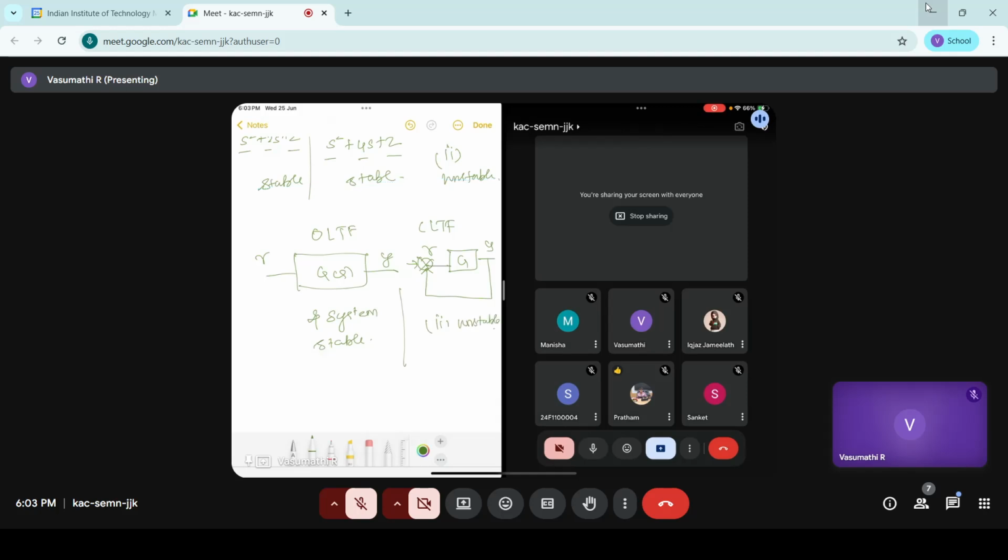So sometimes this feedback creates a disturbance inside the system that makes a marginally stable system go from the midpoint, the marginally stable, to unstable. That is the case that happened in the right hand side. So this is some intuitive explanation behind that. The marginally stable can anytime be stable or unstable. In the system behavior, based on the other pole location, it pulls the system towards the right half of the s-plane. That makes it unstable. Clear?